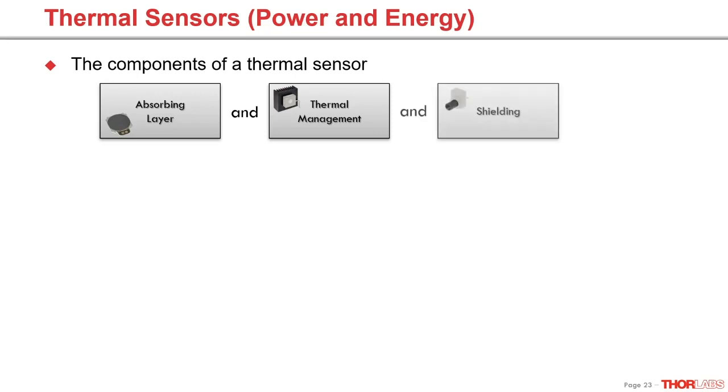For measuring the lowest power levels with thermal sensors, it is important to shield the sensitive area from black body radiation, because the sensors react to every heat source. So if you move in front of the sensor, it will pick up your radiation as well. Further, there shouldn't be any air vents or ambient temperature changes.